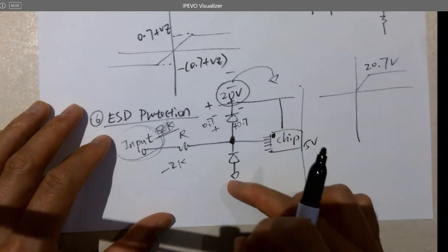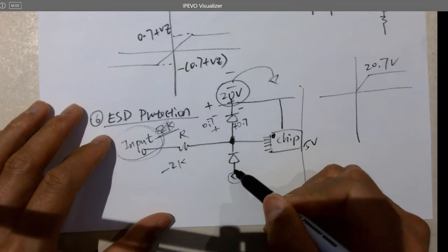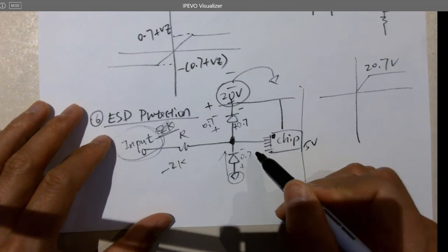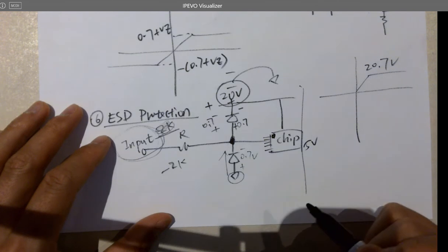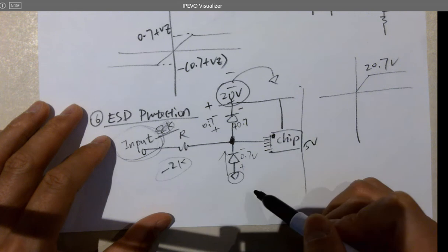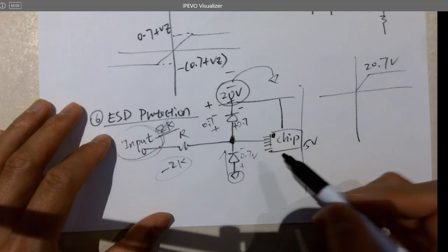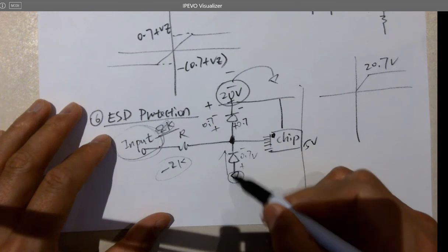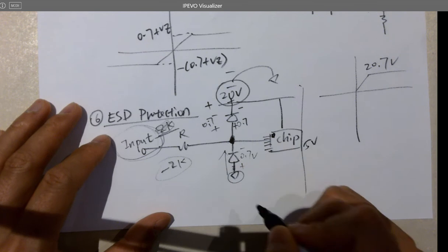But the thing is, you got a 0 here. If you got a negative voltage here, then this becomes conductive, and it's going to drop a constant 0.7 volts across it, right? So no matter what voltage it is at the input, it won't increase anymore because it's going to run a lot of current to drop that voltage across the diode. They probably need a little resistor.